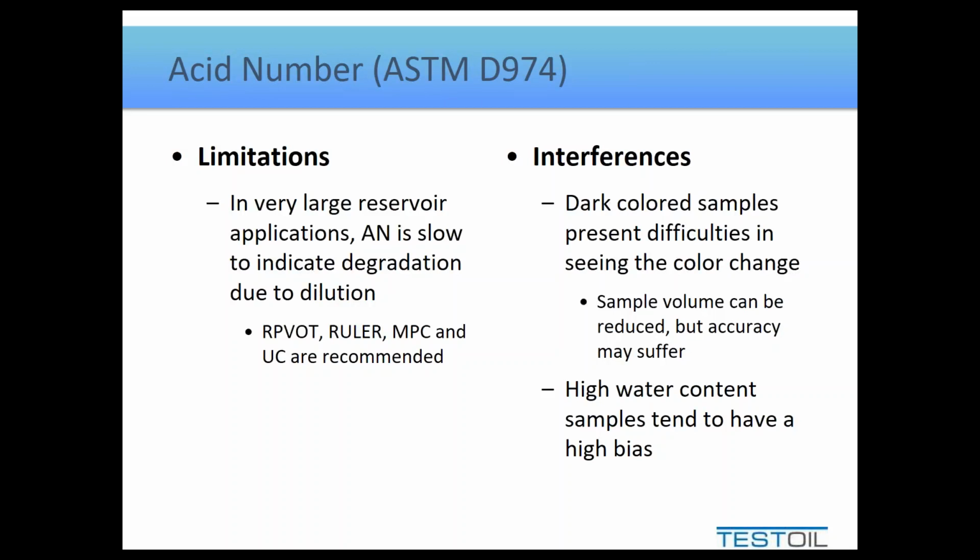The limitation to this test is that it is going to measure acidic constituents in the test, and these build up typically rather slowly, and they're a measurement of a concentration. So the larger the volume that the reservoir or sump is, the slower this particular test is to react to degradation. By saying that, what I mean is in large reservoir applications, we tend to rely on other testing to indicate severe degradation is occurring.